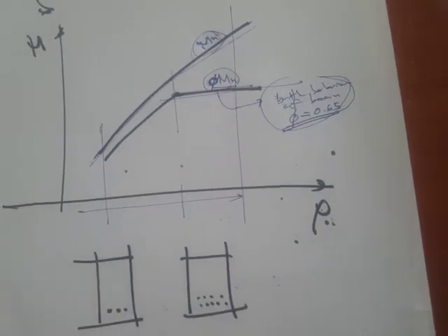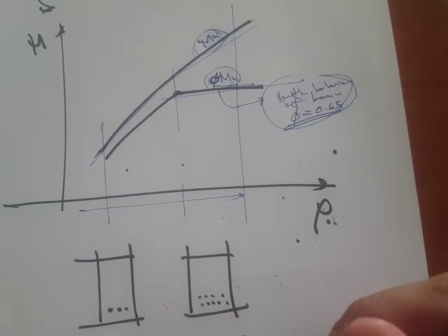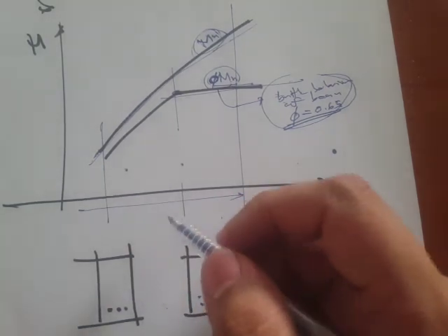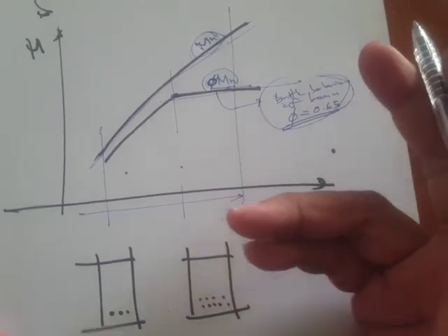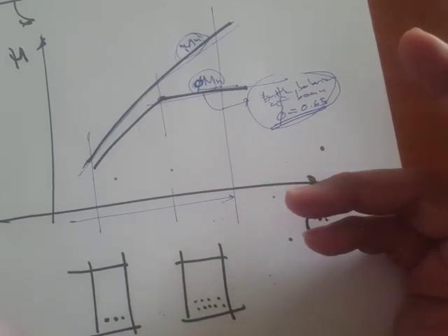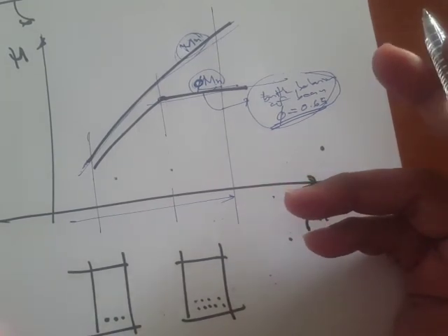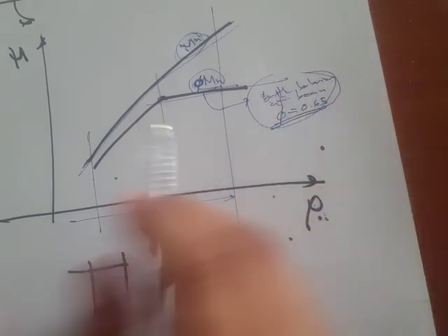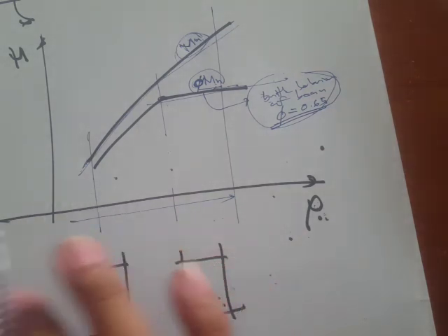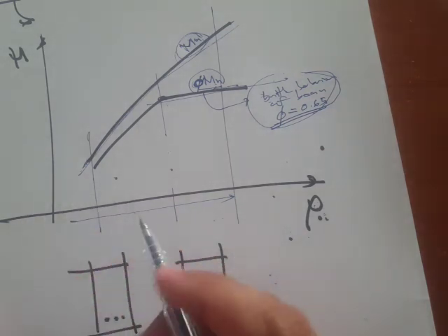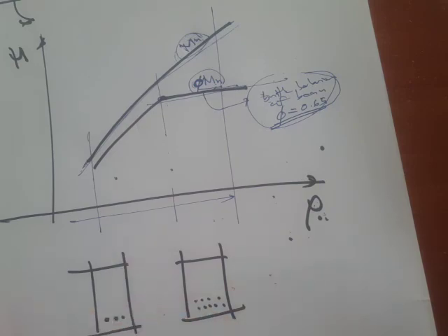The point here is that what we want is a ductile mode of failure for beams, because ductile failure gives warning. Again, ductile failure means that there's going to be deformation of the beam before it collapses.